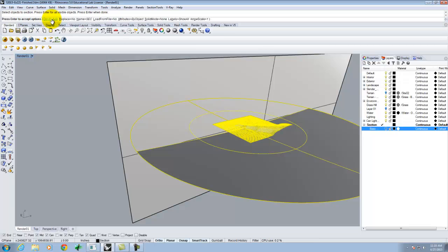Right, so let's say I had my object here, something like that, and I'm cutting this section here. Right? I have an x and a y axis. Obviously, I'm running in the x-axis. I can, however, cut a section at some odd angle if I want, in which case I'm going to click where it says direction x-axis, and then there'll be an option for pick. And I can choose my own axis. Okay? Which is, again, where it's really useful to have the big section plane because you just copy what that is. For right now, I'm just sticking with the x-axis.